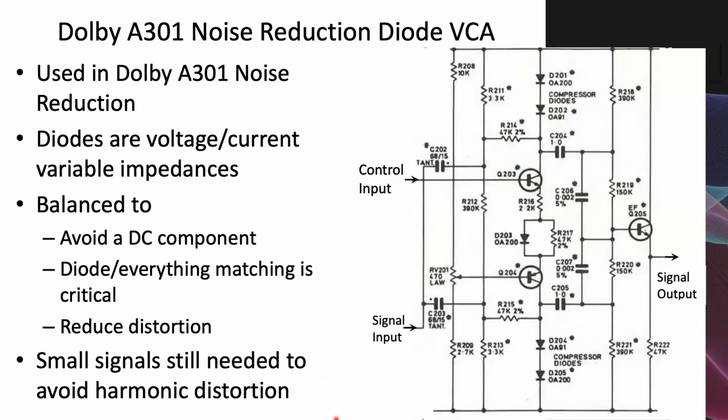This is the same system that used FETs when the later versions came out. But here we have them using a diode compressor, actually two series diodes, a germanium and a silicon one. I think that was to try and get a softer turn on characteristic and lower distortion.